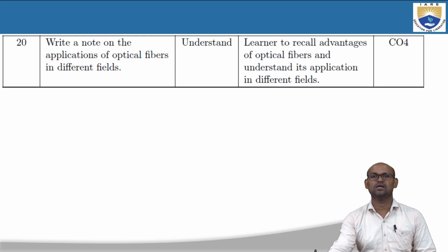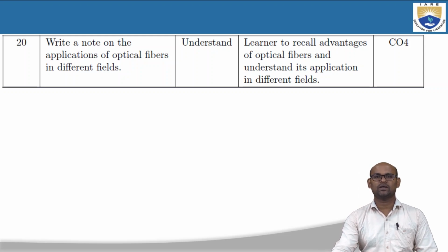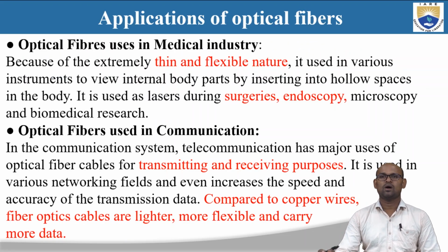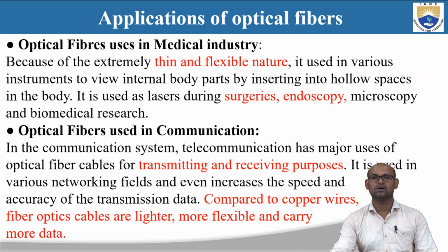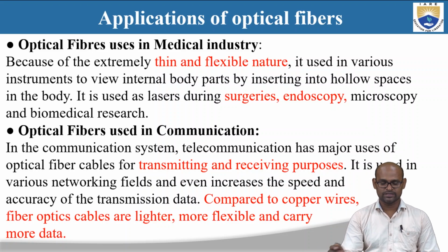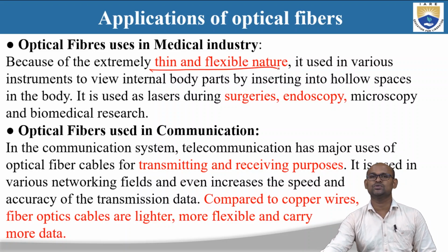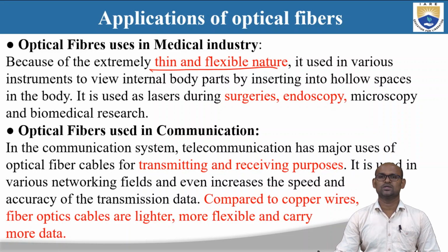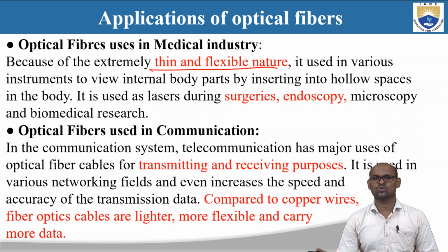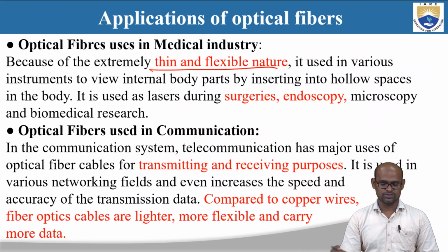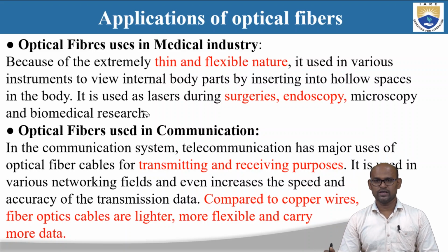The 20th question is: write a short note on the application of optical fibers in different fields. Optical fibers have many different applications in various fields. The first one is in the medical industry. Because of its extremely thin and flexible nature, it is used in various instruments to view internal body parts by inserting into hollow spaces in the body. It is used as lasers during surgeries, endoscopy, microscopy, and biomedical research, and also used in communication for transmitting and receiving purposes, because it has very low loss of signals.